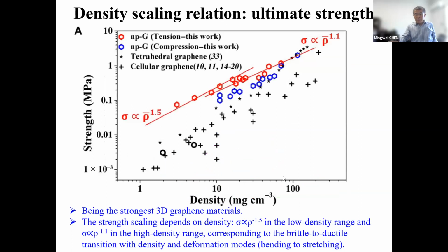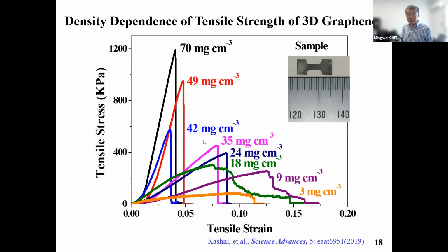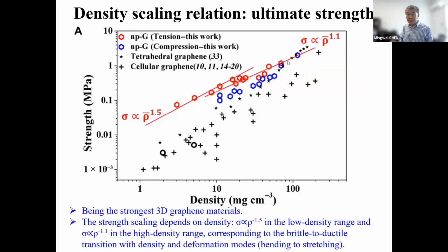To deal with this kind of porous material, for the comparable strength, the modulus, how strong, how weak, somehow you have to really consider the density. You have to do the scaling relation, use density to scale your strength, so you can plot it together. We call this density scaling of the mechanical property for the porous material. This is the result. We do the scaling by density for the tensile strength. We know the density, so we can plot these scaling relations here.